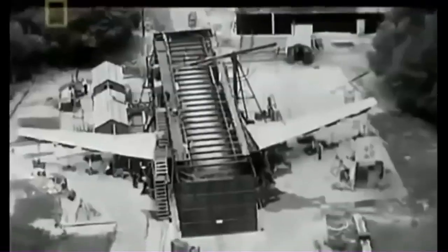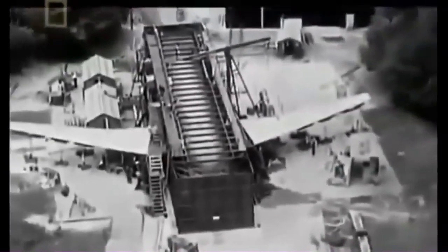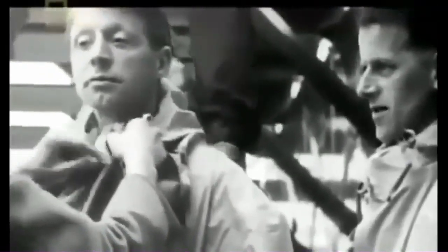Engineers fill the tank and the plane with water. When they are both full, they force more water into the plane, pressurizing it as if it were flying. After 5 minutes, engineers reduce the pressure. Each test puts the same amount of strain into the aircraft as a single flight at 12,000 meters. Sir Arnold plans to test the fuselage to destruction. It could take up to 5 months. The experiment runs 24/7. Using 1950s technology, it's a grueling task.